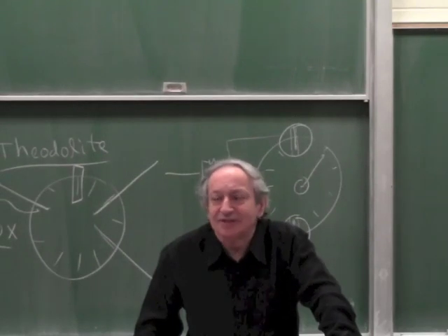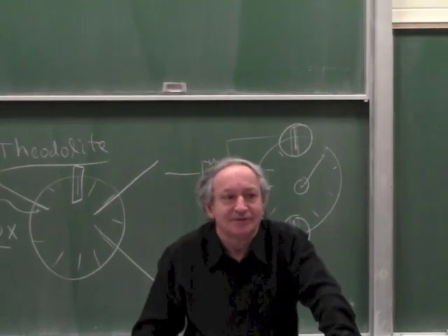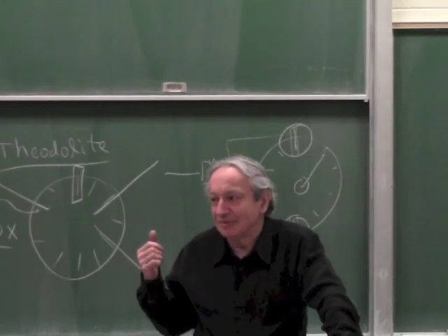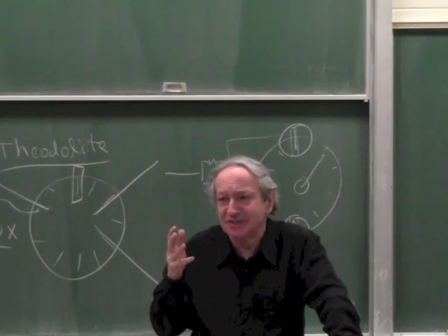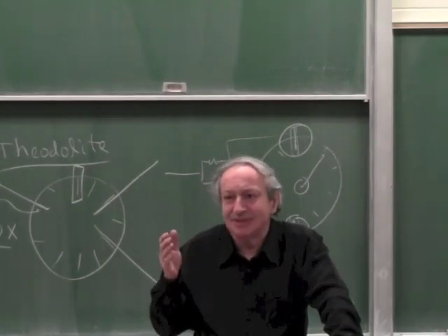Besides differential, what else did we do with an optical sensor to be immune, say, to the light in this room? Filter. Well, you can do this in a camera too. You can put a filter in front of a camera, although color cameras have their own filters, so you can only filter within the visible. But something else.